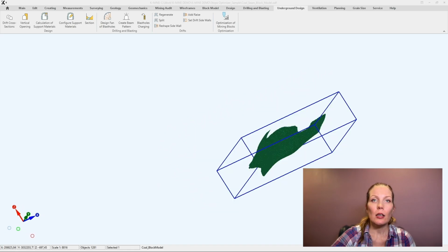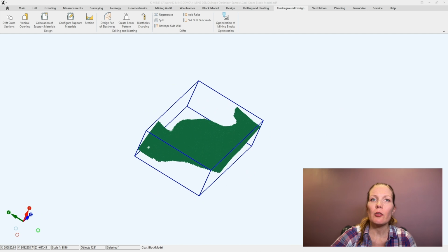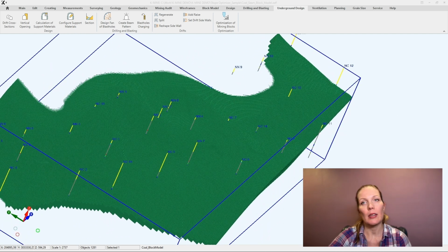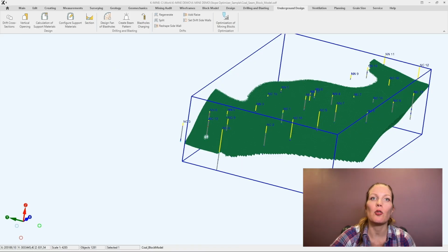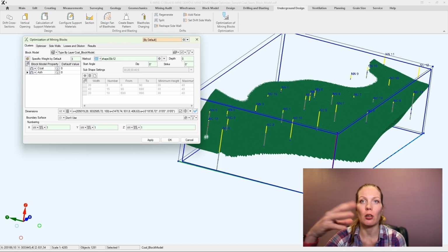Another key feature is the ability to restrict the optimization domain. Not every geometrical stope is practical at a given stage of development. Some areas may be inaccessible from current levels, located within the influence zone of active stopes, or positioned under protective pillars. In K-mine, the engineer defines the working volume, the portion of the model where extraction is currently allowed.